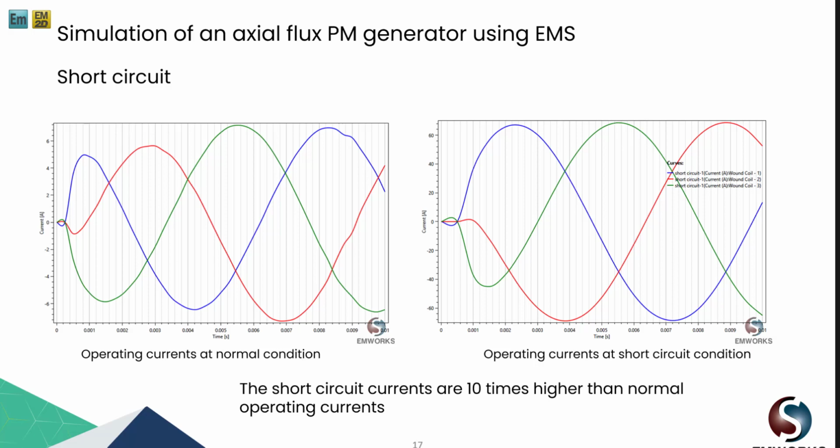So this type of analysis, of course, you can go to the lab and experiment with, and of course, waste a lot of money and time. You can actually do the simulation right in EMS. You test your short circuit, and you know why it's important to do a short circuit run, to know your current in case of a short circuit. So you're going to have the proper fusing and proper protection of your valuable investment.